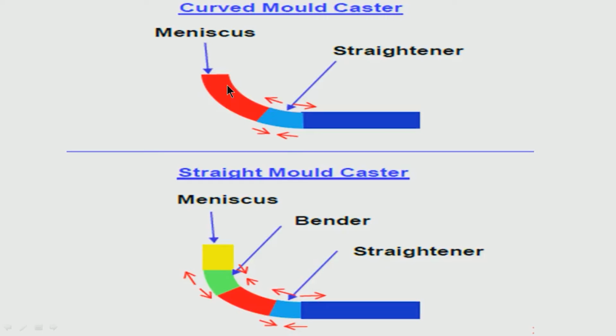So in a situation where we have a curved mold, the uniformity of inclusions in the cast product will not be there. Certain portions near the inner radius will have more inclusions, and inferior quality. But if you have a vertical mold, that possibility is not there; it will be relatively uniform.